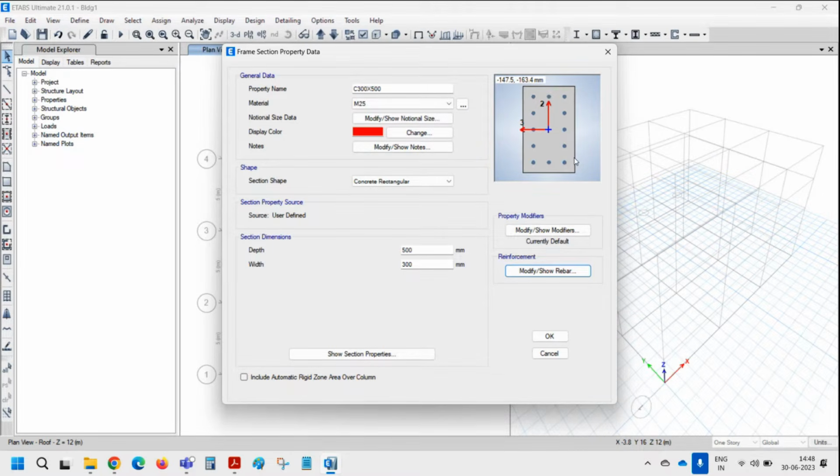This is important in the column design because program does not use SP16 PM interaction curves, but it will generate PMM interaction surface full 3D for the design. So this is explained in the design manual in detail, but obviously it is what is used in the column design, generation of PMM interaction surface for various shapes.